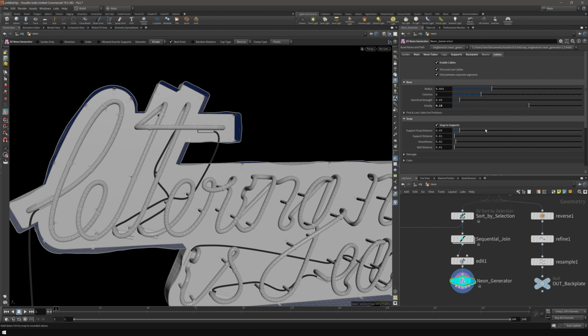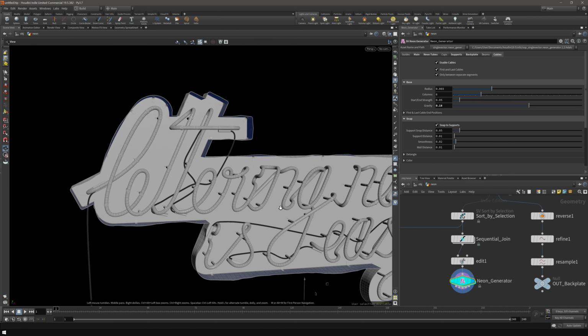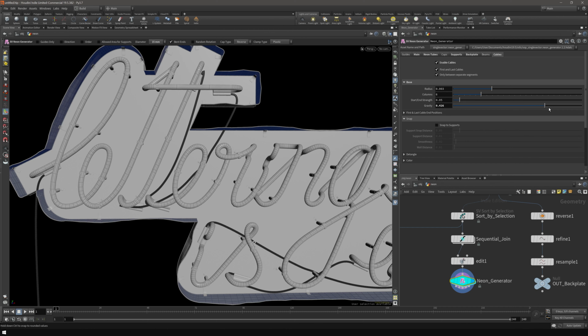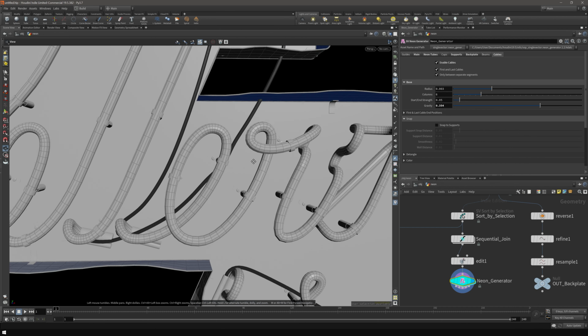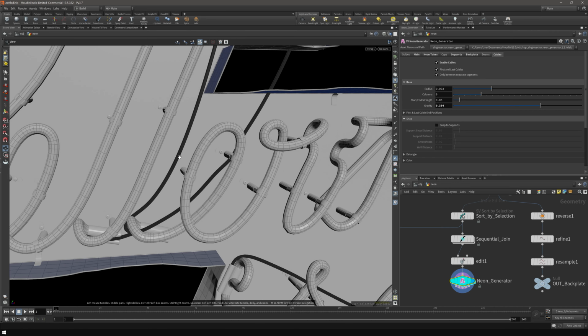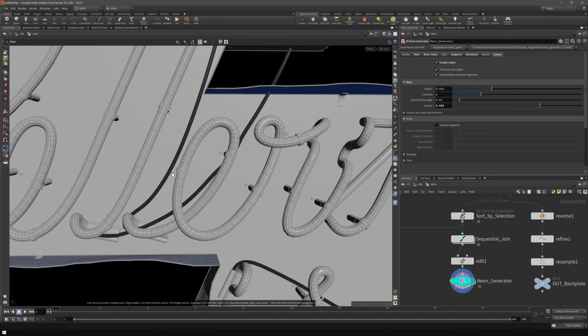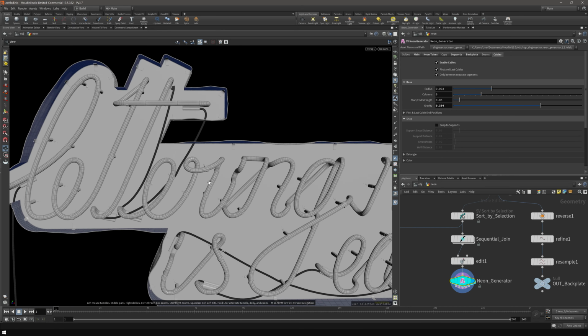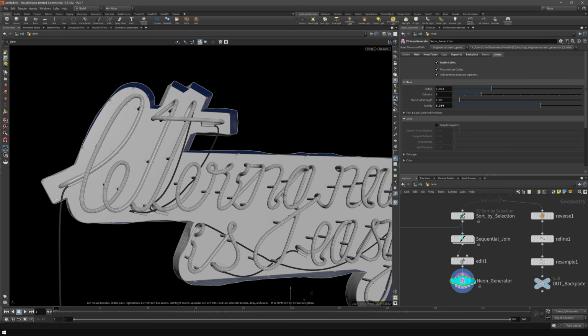So snap to supports, and sometimes that can solve the situation. That just means that it will not just freely hang like that. Basically, if this cable is very close to this support, it will snap to it, or this will snap to that one, or maybe even that one. So in that way we will have a little bit different layout of the cables.